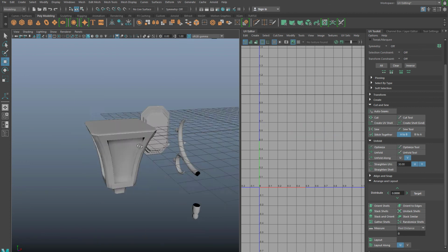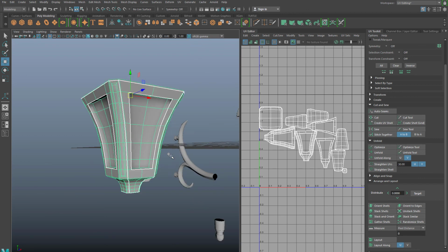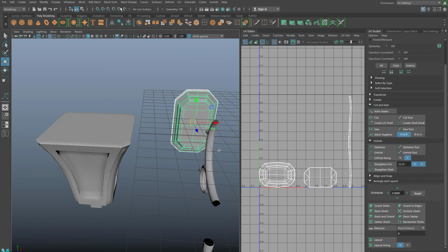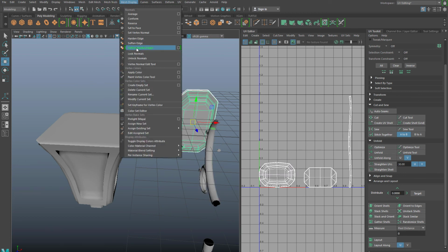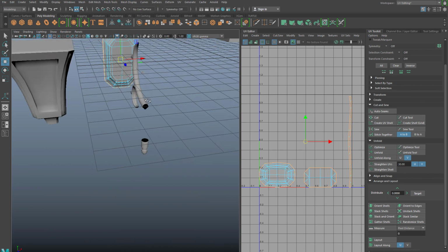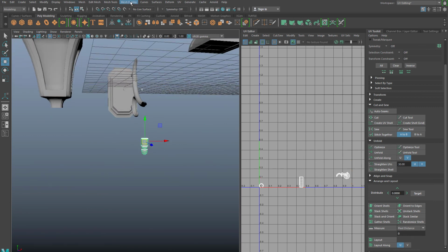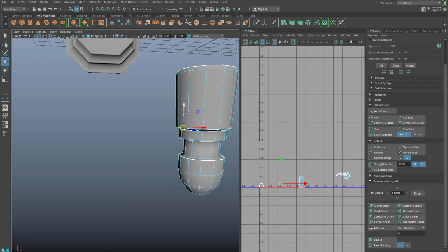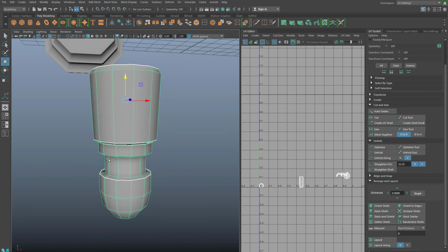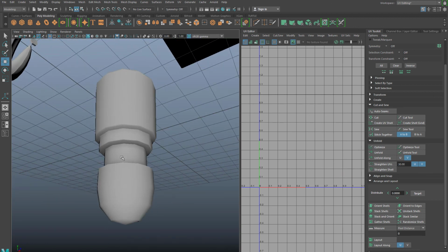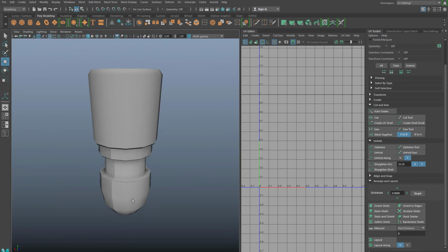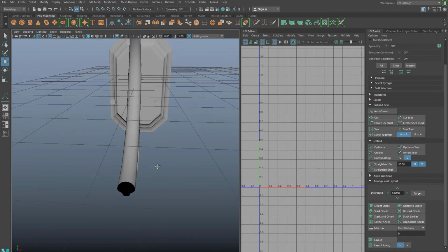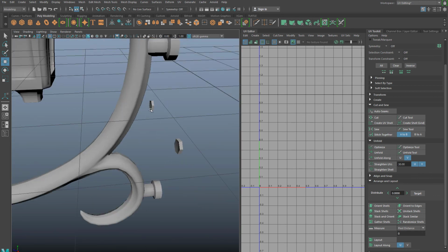So you may have to do this on individual objects. So mesh display, soften harden edges, mesh display, soften harden edges. And you'll notice the shading will change each time you do this. So in this case, the object, hit F, and we look at it, you can see where it's firmed up the edges and even shows a little seam back here. We need that so that we don't get the baking errors.